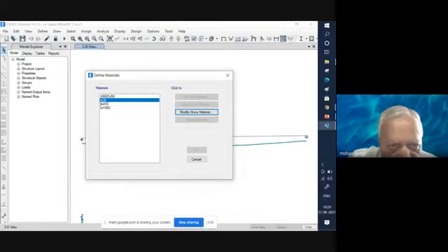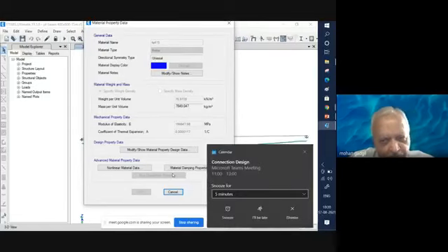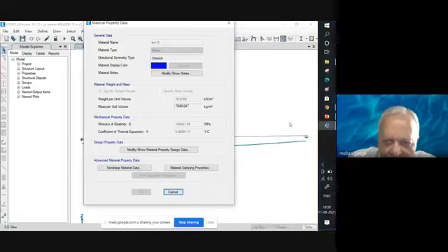As far as normal steel is concerned, it is Fe415. So I have considered Fe415 as a normal steel because I will have to design the stirrups later on. And also, though I am using prestressed concrete, I need to consider the moment resisted by prestressed concrete.